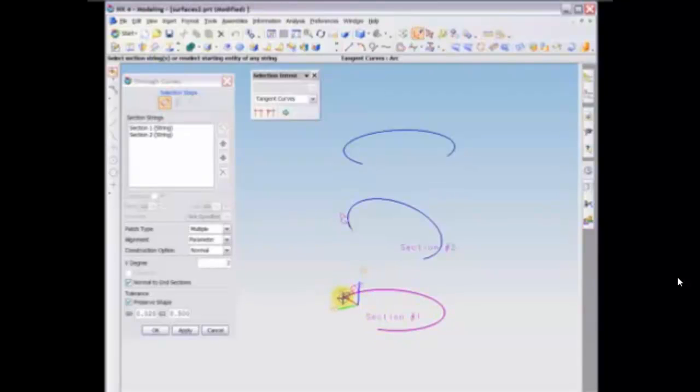If you are using open curves for your profiles, the endpoint nearest the pick point will be the start of the curve, and one edge of the surface will travel through each of these points. Thus, the surface may become twisted if your endpoints and directions are not correctly specified. Direction of the curve is important when using closed curves as well. You can reverse the curve's direction by deselecting it and reselecting near the other endpoint.